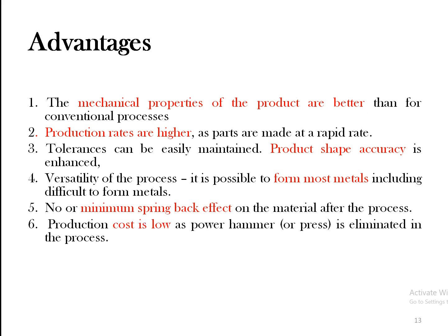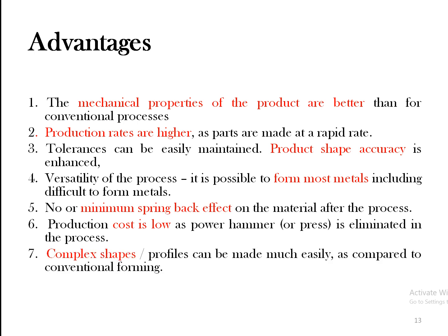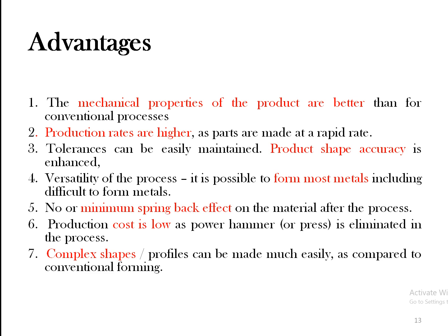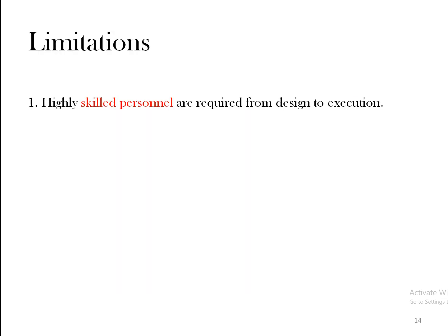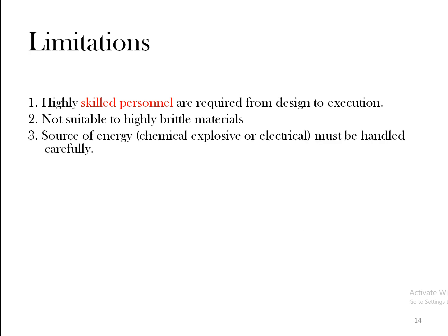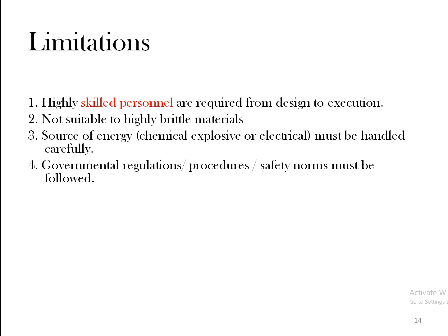And the production cost is very low, as the power hammer is eliminated in this process. Complex shapes and profiles can be formed using this process. These are the basic advantages, and the limitation is that it requires skilled personnel to design and execute. It is not suitable for highly brittle materials.